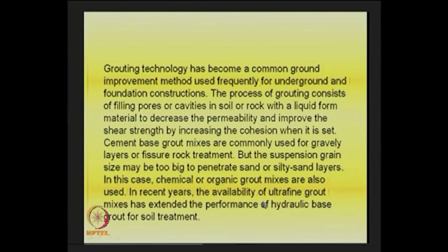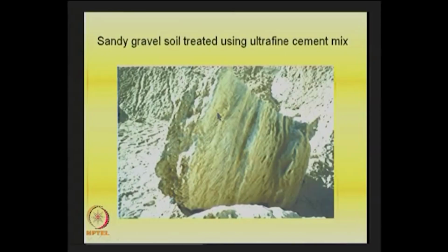And nowadays we have even ultra fine grout mixes which are quite useful for increasing the performance of hydraulic base grout for soil treatment. If you use this material, it is going to be very useful in trying to reduce the permeability and increase strength and all that. I would like to just show you a typical photo in which sandy gravel is there initially, but then if you mix ultra fine cement grout and remove the soil mass, it is like this, it is so strong.